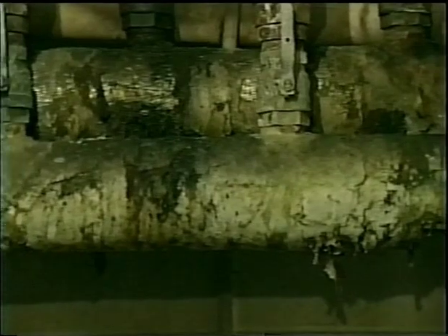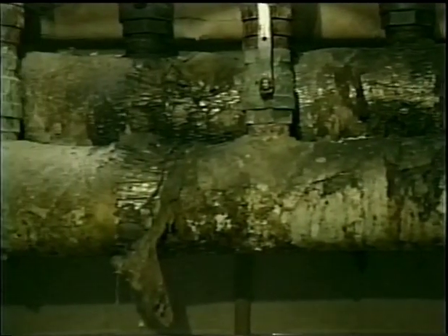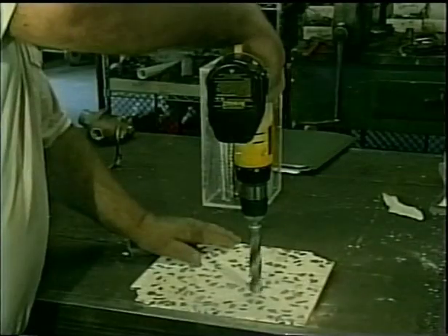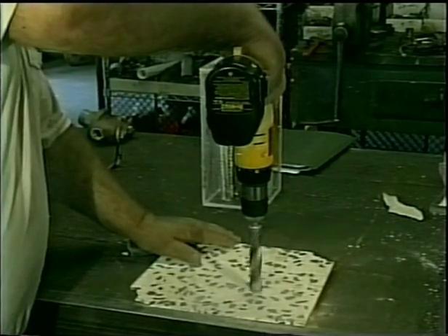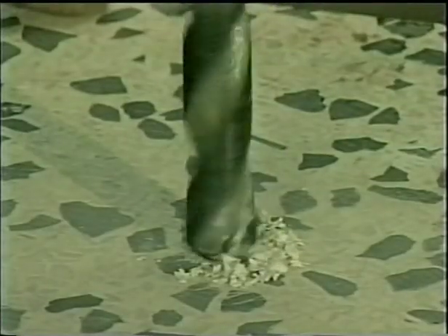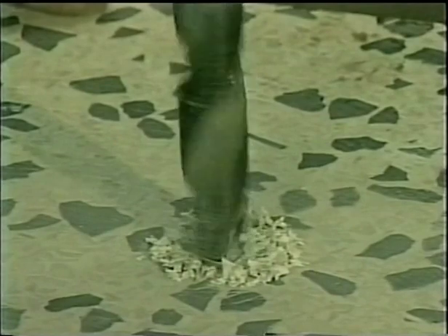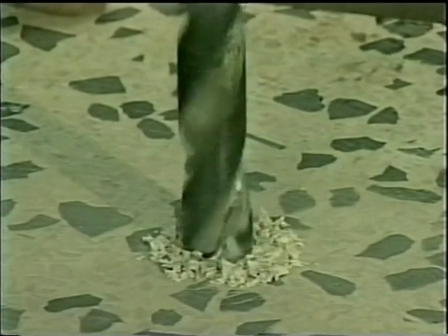Another source of damage is aging. All materials become more brittle as they get older. Floor tiles, pipe insulation, and other insulation materials all suffer from the effects of aging. As materials get older, they're more prone to damage from any source, thus releasing fibers into the air. Physical impact such as drilling, grinding, buffing, cutting, sawing, or striking can break down the materials, also making fiber release more likely.